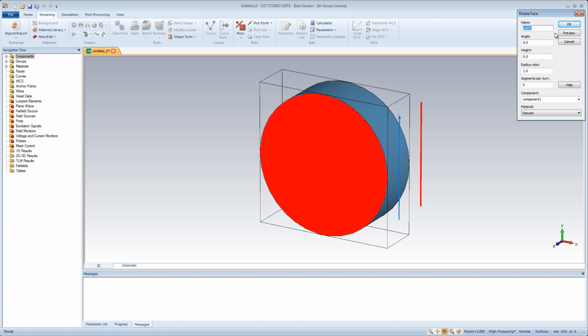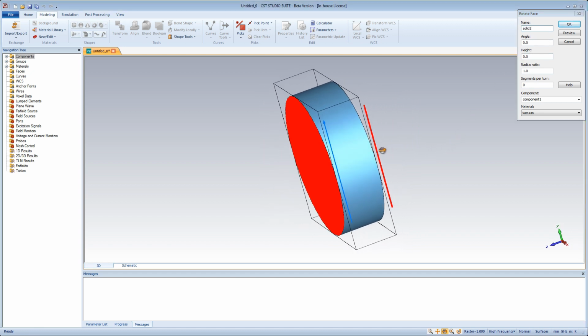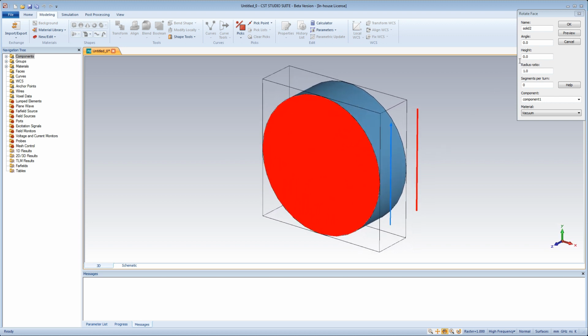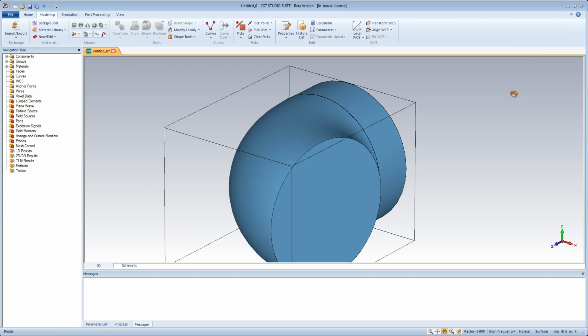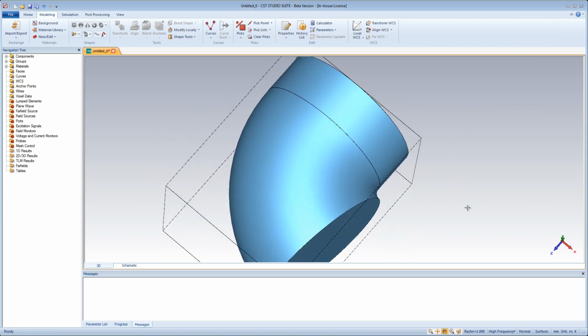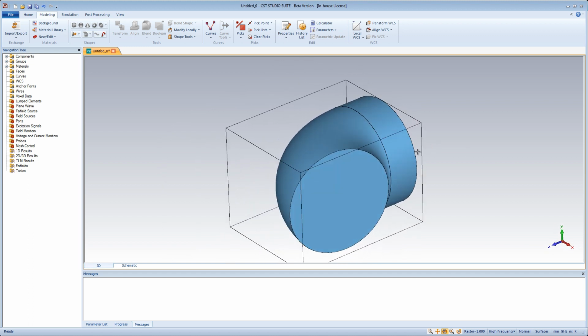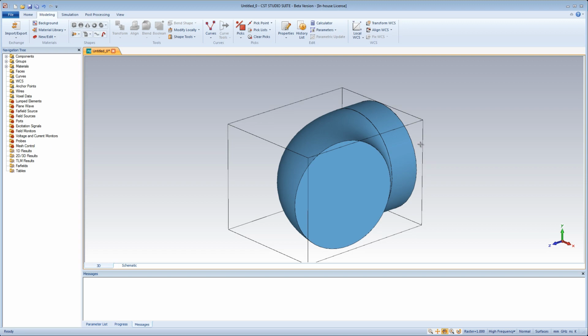Afterward, you can activate the Rotate Face tool by selecting Shapes, Extrusions, Rotate. The previously selected rotation axis is automatically projected into the face's plane. In this dialog box, you can specify an angle and click OK. Note that the Rotate tool enters an interactive polygon definition mode similar to the one in the Extrude tool if no face is picked before the tool is activated.